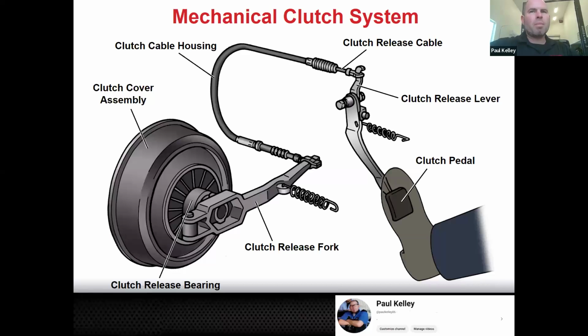He came back so happy. He's like, it hasn't shifted this well since I got it, and I thought it needed a clutch. And I've had the car here for like 8 years, and I didn't want to pay to have a clutch done. And I was sort of like, yeah, man, the whole time it's a $20 cable. So the cable can really throw you off. In the rare event that you're working on something older with a cable, the best way to test it is to eliminate the clutch from the equation and see how just the cable moves. Cool, that's what I would do.